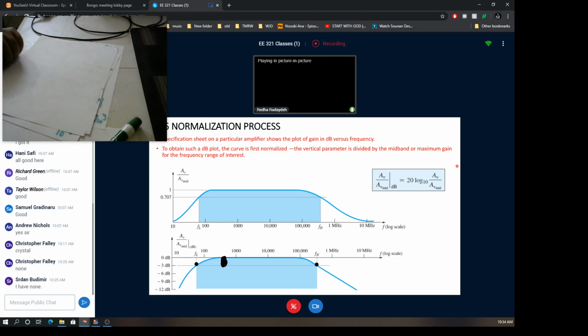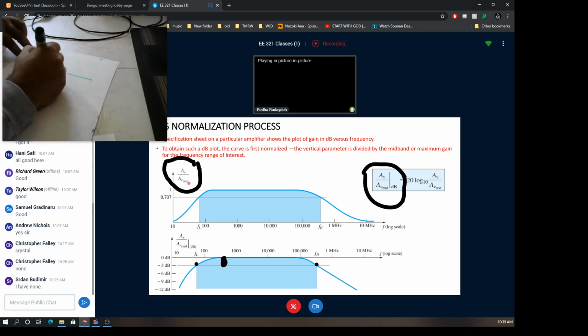The last thing to talk about with this figure is the normalization of the gain. Usually we express the gain as a ratio with respect to the maximum value. Okay. For example, if you have in decimal value this frequency response representing a certain amplifier, this is AV, magnitude gain, okay, whose value is 100.